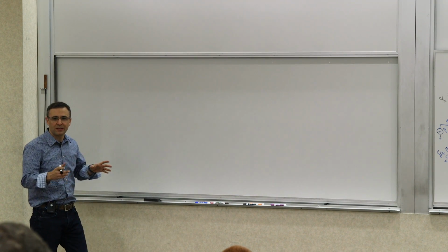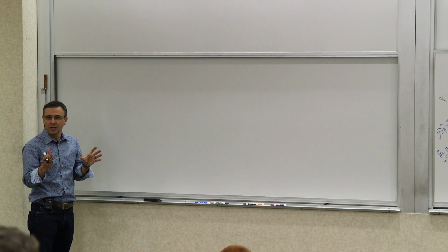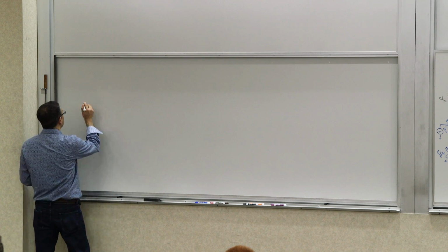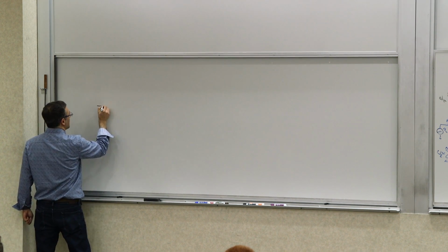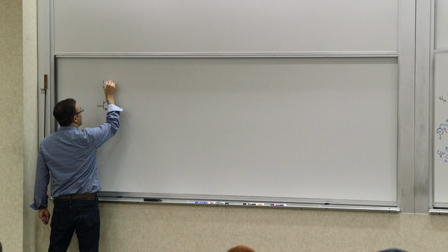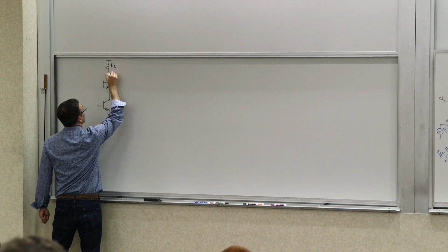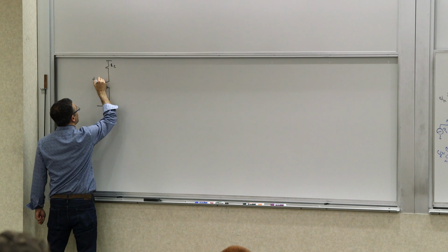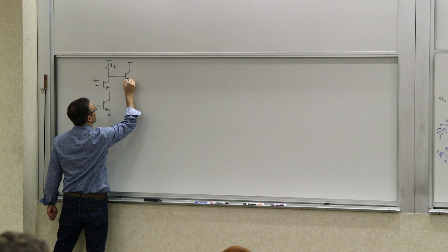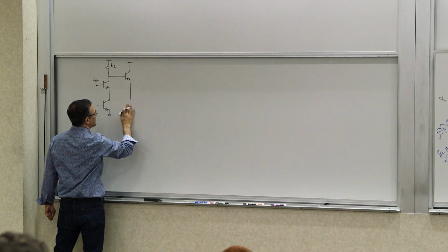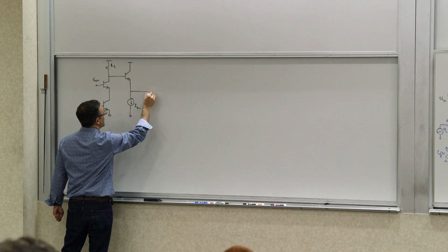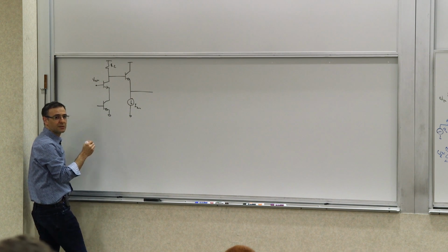And then from that point, we created some conceptual design, right? So the conceptual design we had then was something along the lines of this. It can be bipolar or MOSFET, doesn't matter. I'm showing it with bipolar because that's a little bit more general. So we had some V bias here, and then we had a buffer stage, a follower, with, I believe, a current source at the time, some I bias, and then driving a capacitive load in that case.